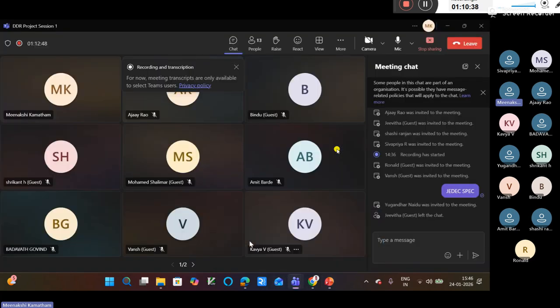They might ask questions like how you verified in the scoreboard, how the signals are happening, how the controller converts all these things, what the work of the PHY block was, in DRAM which types of ranks you used, using rank selection which signal you use to select that particular DIMM, and which bank group, whether both bank groups work similarly.